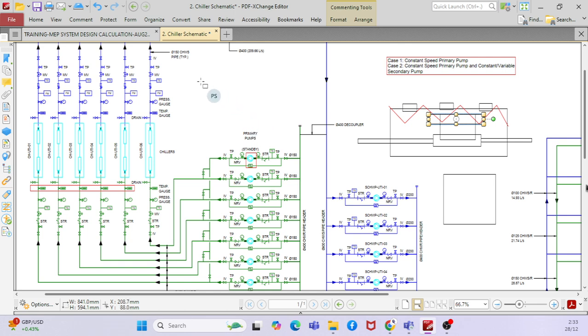See what I'm saying, Q equal to m Cp delta T, the basic equation. Do you agree that when the flow reduces, the delta T will go up? It should go down, right? Because it's directly, no, opposite. See, for example, 10 equal to 5 into 2. When you reduce the 5, the 2 has to increase to make it 10, right? 10 is constant.